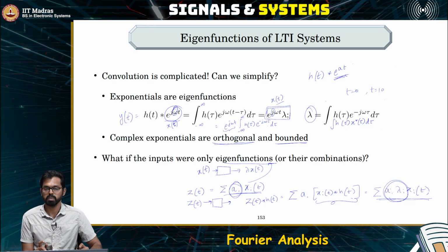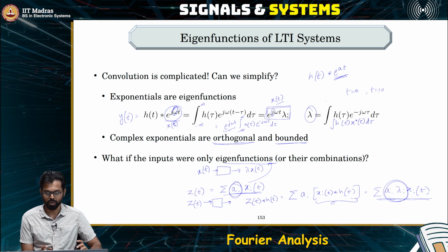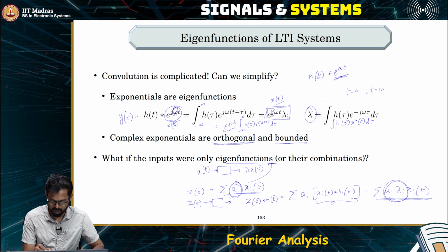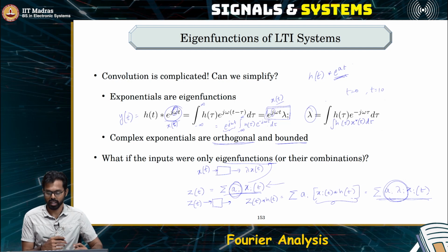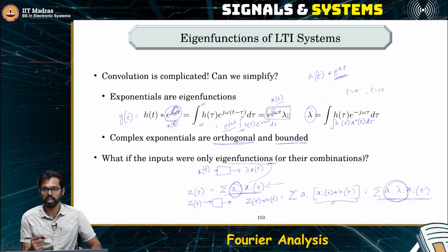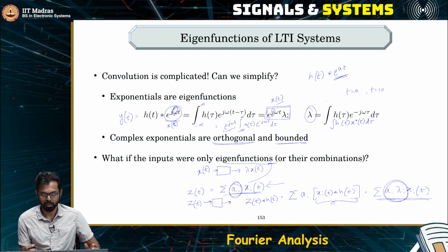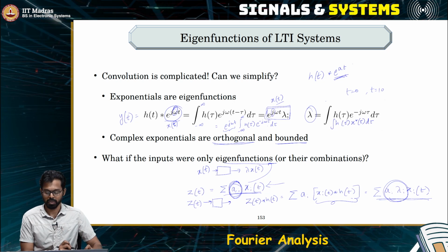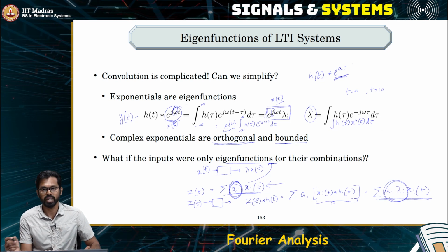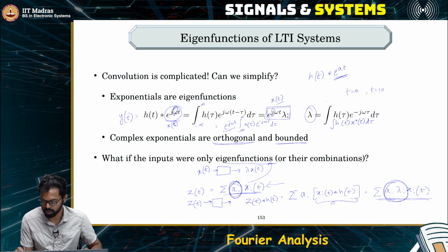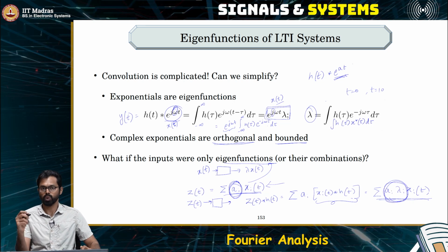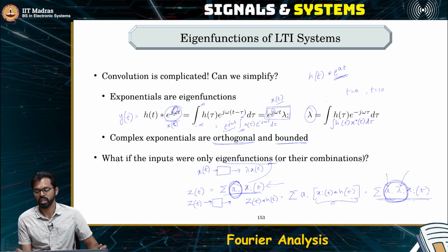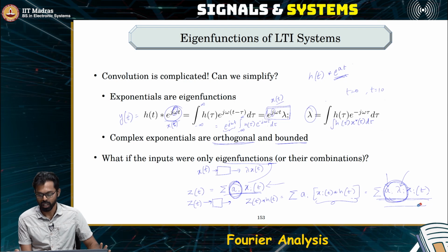Keep this in mind, this is something which we do repeatedly in Fourier transform. All you do is take the input signal and decompose it in terms of the eigenfunctions. What is this decomposition? Essentially, all you have to do is find these coefficients. That is a decomposition. And how do you find the output? The output is simply the multiplication of these coefficients with the eigenvalues, and then putting everything together, we have found the output.